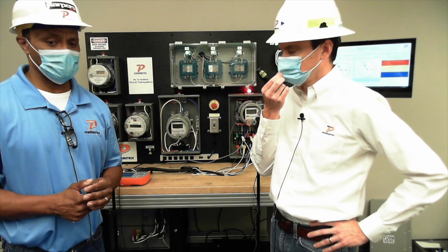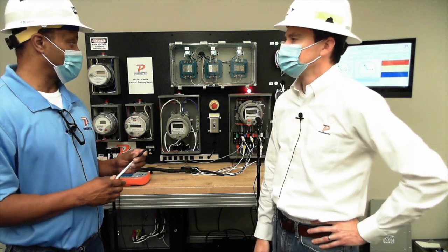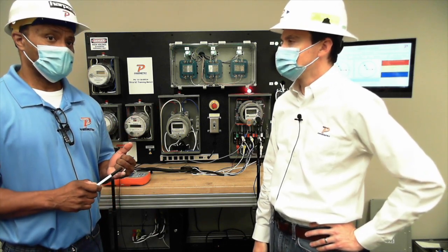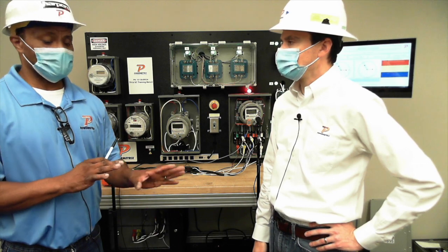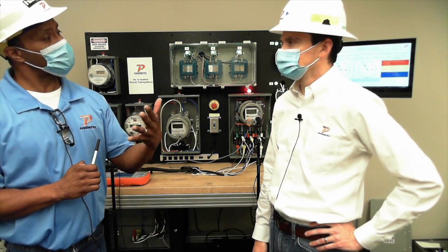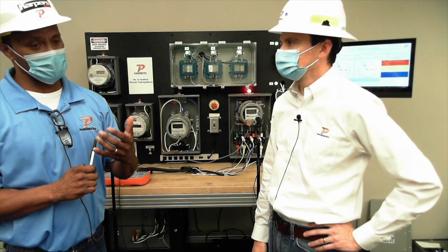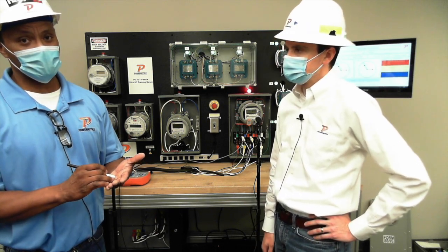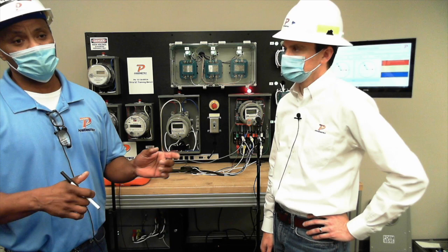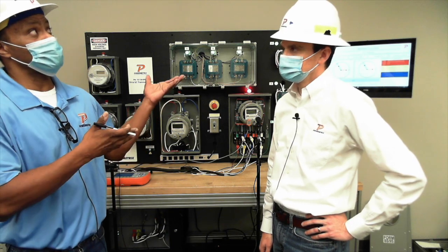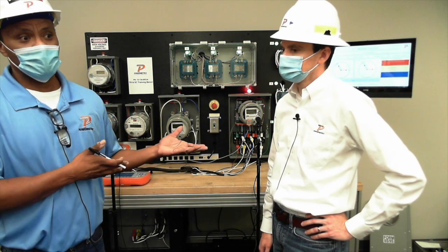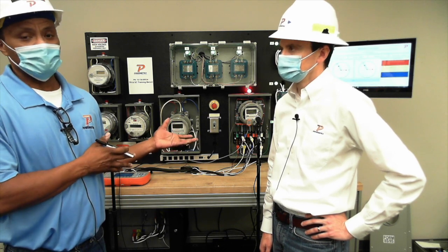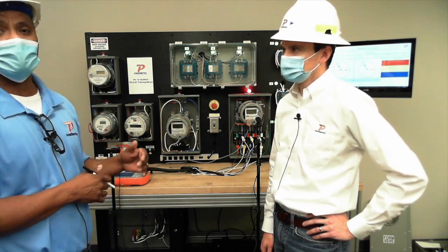You might have some, and believe it or not, I've actually run into a meter that tested fine, but the register wasn't accumulating. So there was no energy and no power. But it tested fine. The good old faithful, when I wrote the kilowatt hours down, when I was bagging everything up, putting it in the truck, I went, wait a minute, and it's a huge building, I'm like, how come this meter has not moved? I said, that's not possible. So I knew right then that the register was bad.